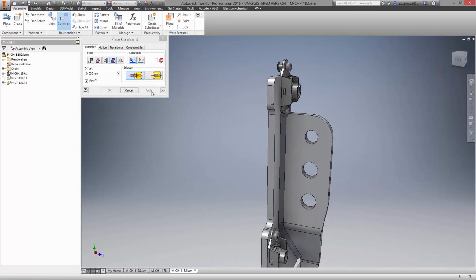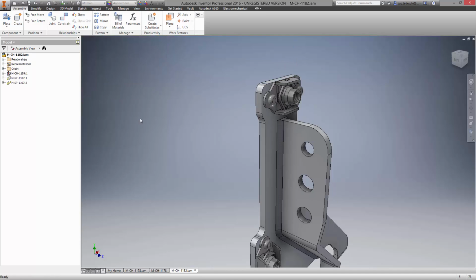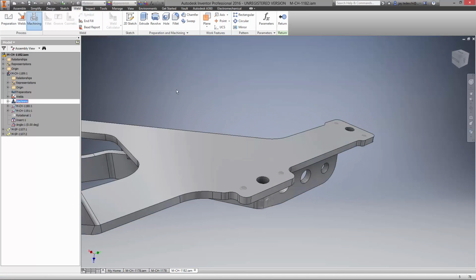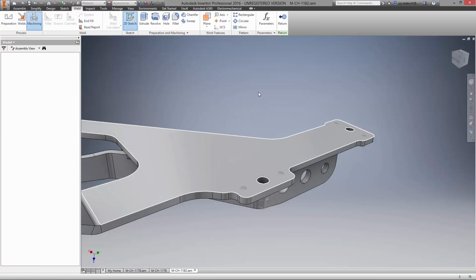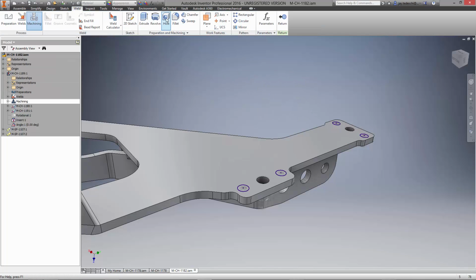Notice that the anchor nut contains 2 rivets to fasten it to the sheet metal component. Autodesk Inventor enables users to create the holes for the anchor right in the context of the assembly. Simply click on the part to edit and refer to the rivets in a new sketch. Reduce scrap by ensuring holes that show up in the detail drawings are never misaligned during assembly.